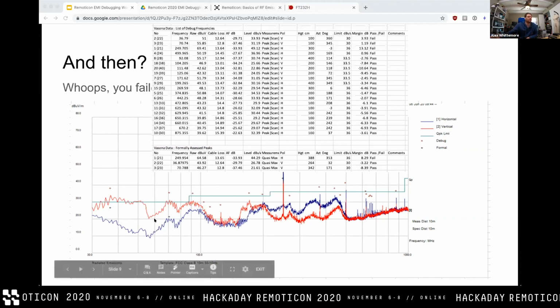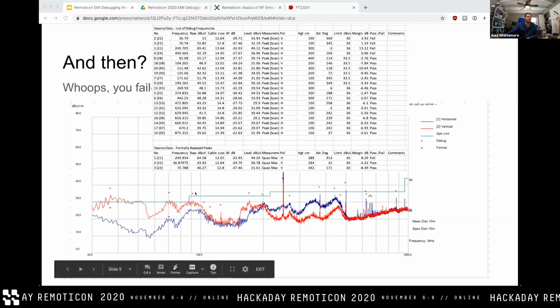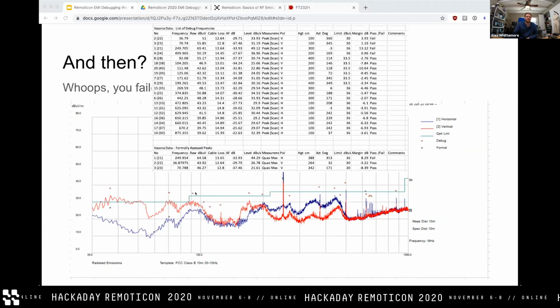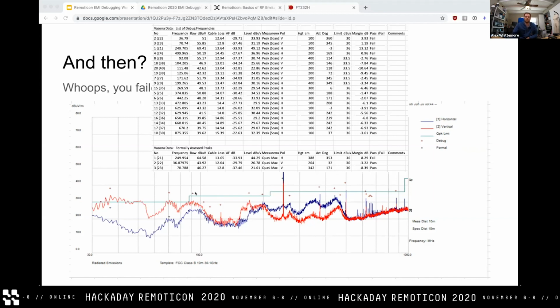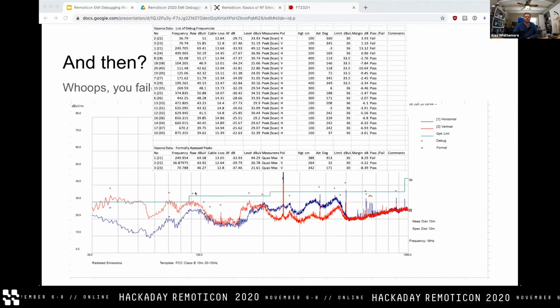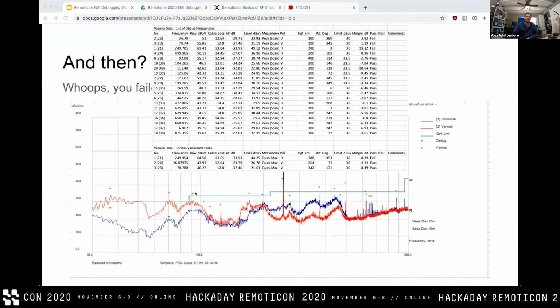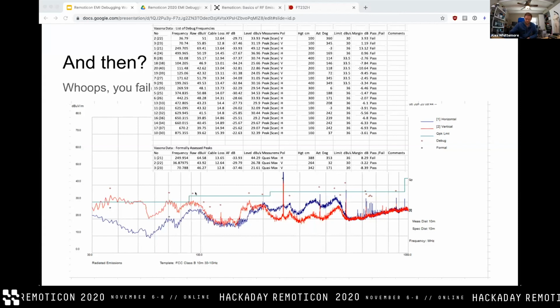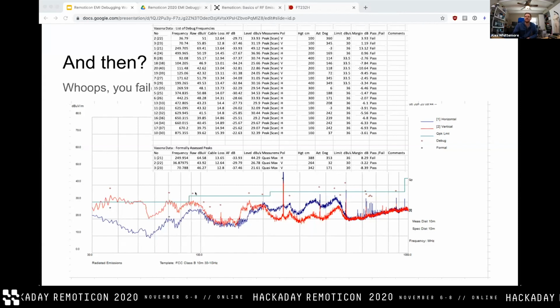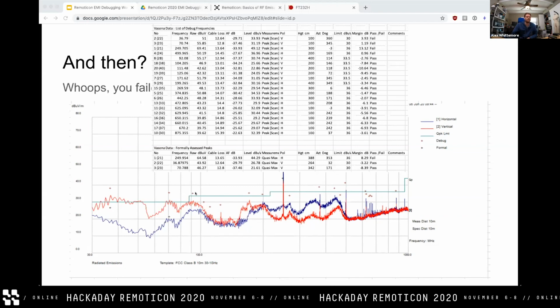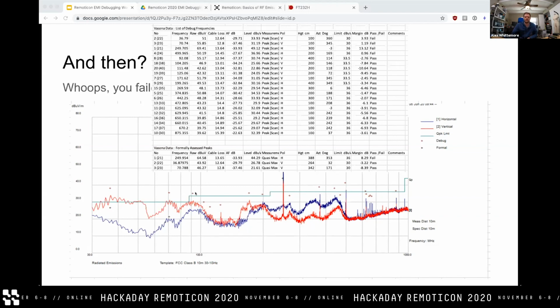This first phase of the test, where it lists debug frequencies, is sweeping the spectrum analyzer across the entire spectrum and looking for only the peaks at each point. So looking for the absolute maximum value of RF power that we see for every point in that spectrum. Well, devices behave differently throughout time, and maybe your device is chirping really loudly for a moment.